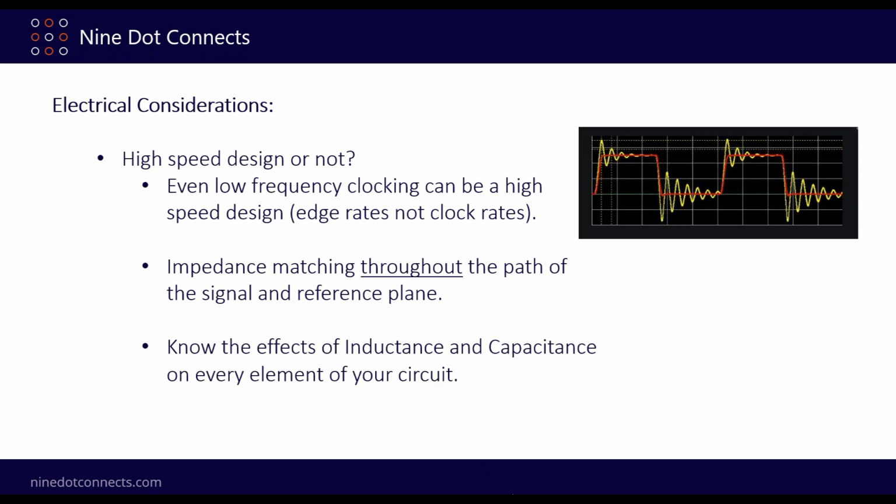And know the effects of inductance and capacitance on every element of your circuit. It's such a simple thing, inductance and capacitance, but if you don't think of it very often, you kind of need to start thinking about it. So it's one of those things where you want to always remember the effects, especially on high speed, of inductance as the frequency increases, or the effect of capacitance on your designs. We're going to go through that a lot in our training, and so that's just one thing I wanted to bring up, and hopefully everybody can go out and learn about that.